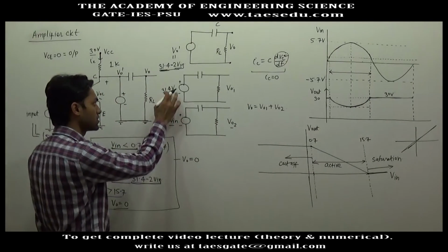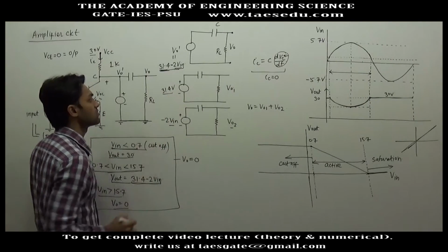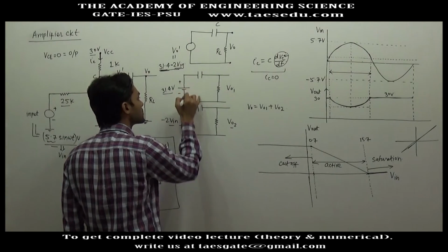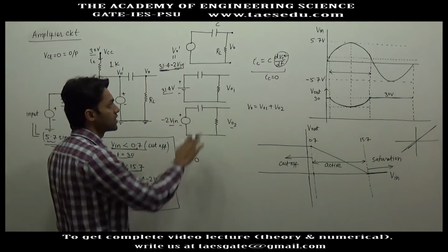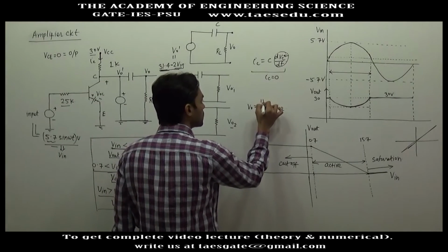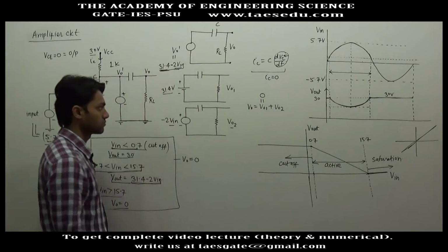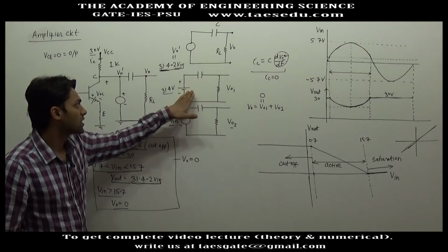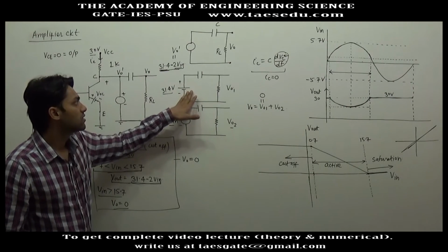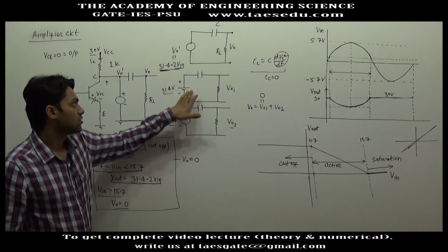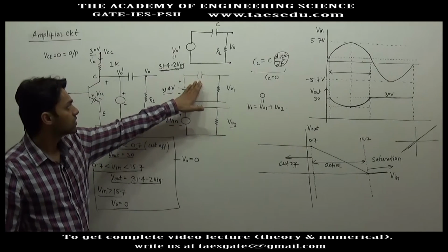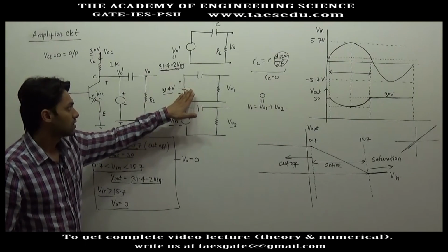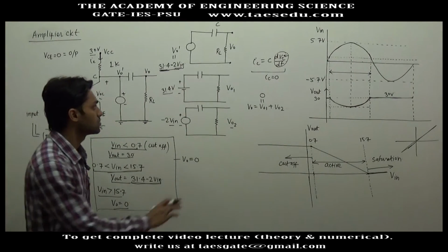Now talking about the first input, this is again a constant voltage source, so this will be a DC source, and in a steady state there will be no current, so V01 equal to 0. So now can you say how the capacitor is blocking DC? In the steady state there will be no current due to this voltage source through the capacitor. So what is the role of the capacitor? The capacitor blocks DC voltage. So V01 is 0.